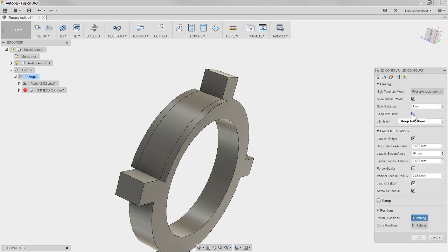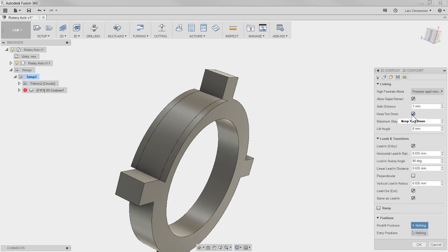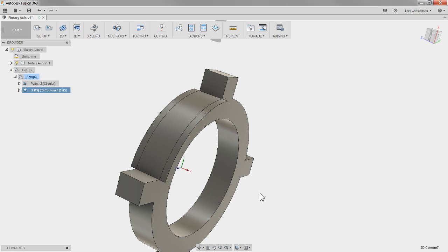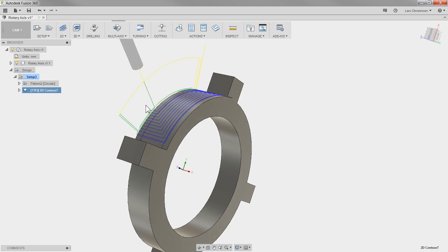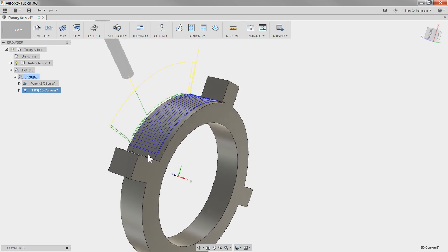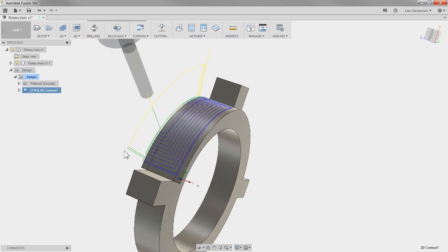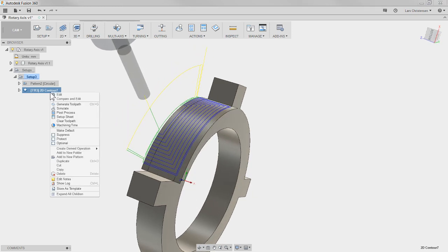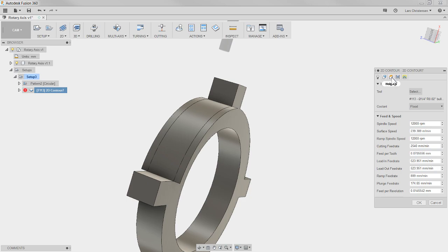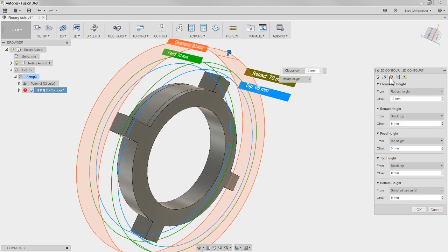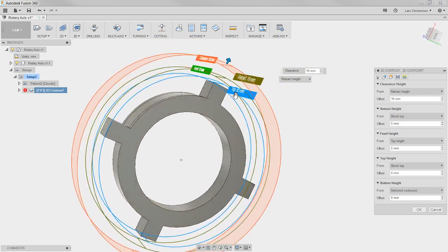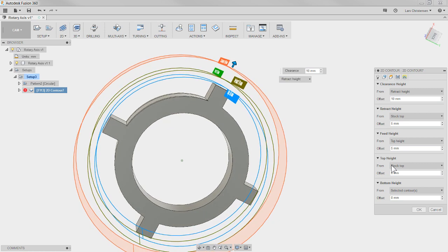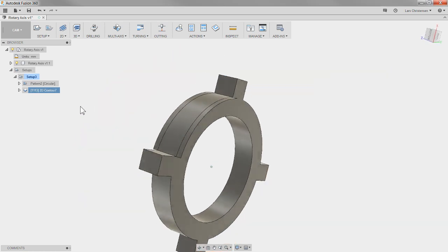And here I just use the keep lift down, and then you will see that it's going to come in, it's going to keep it down on the outside until the last 2 passes here. And the last 2 passes, that is all controlled on the heights tab. So here you have the control where you can control all about your retract and how all that is going.